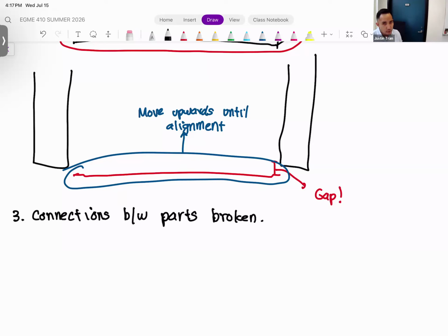And so if you remember from activity three, when we took a look at the connections at that point, we didn't do anything with them, but we saw that our sign and our post were connected by a bonded connection, right? So usually ANSYS will create those automatically. Whenever it detects two parts that are in contact with each other, whenever the part was made, then it'll make those contacts just automatically. But when you're modifying your geometry, you're creating shells and beams, all these connections get broken, right? And so before you can run a simulation, you have to reset them manually.